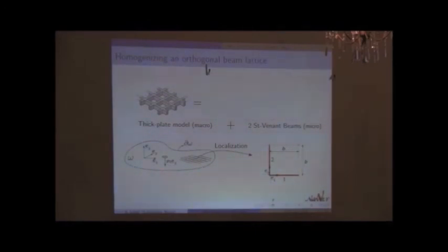And it turns out that if I want to model this plate with a Reissner plate model, since it is orthotropic, and I have this pi/2 rotation, I will have a bending constitutive equation which is orthotropic and cubic, but the shear force stiffness tensor, which relates the shear force to the shear strain, is a second-order tensor, and those symmetries are just enough to have an isotropic constitutive equation for the shear.